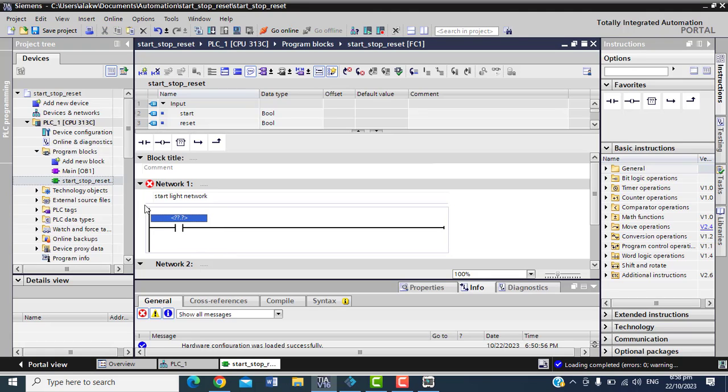First of all, you see this place, we call it the power rail, right? This vertical one is the power rail. And this horizontal one, where I put this normally open, is called the rung. Something that happens here is my signal, my power, is always here, right? Everything I want to do here, like a logic I want to create, will actually turn an output on or off.